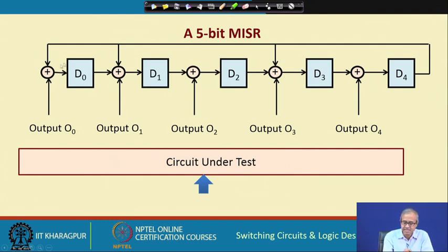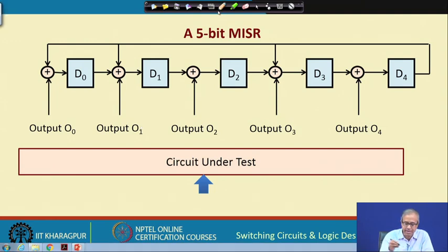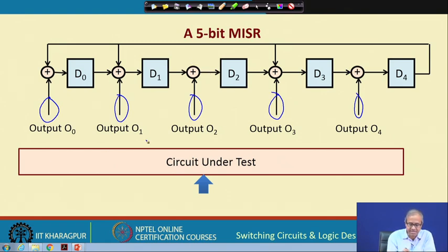This is a type 2 LFSR, where not only am I feeding data in the first XOR, but I am adding an additional input to all other XORs. Even in the places where there is no feedback or tapping connection, I am adding an XOR gate, so that all the outputs can be fed in parallel to all these XOR gate inputs.